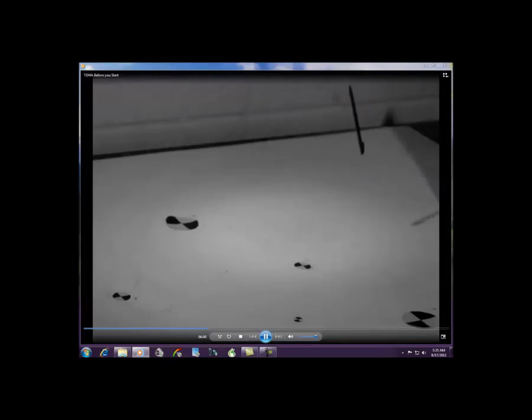So in the second 2 methods described, we need to have something in the field of view which will allow us to redefine the coordinate system so that it makes the test output readily usable. This closer view of the table onto which the pointer is dropping shows the 3 points we have chosen so that we can define a new coordinate system. Point F is the XYZ 0. The addition of point C defines the x-axis, and the third point on the table defines the xy plane. The dimensional location of these points is not needed.